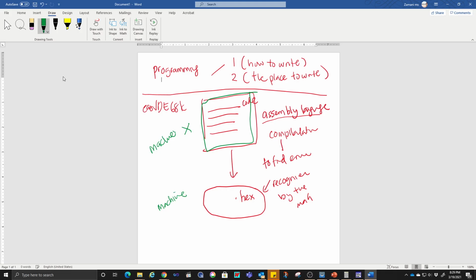In this process, the compiler will detect the errors. Of course, if there's an error, it cannot compile to the correct hex file. If there's a syntax error, that is the main thing you can catch here. For semantic or flow errors, the compiler may not be able to detect them, but all of the syntax errors must be detected in this process.